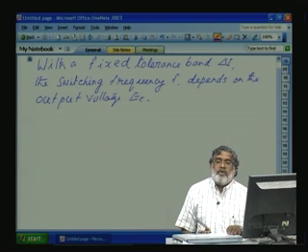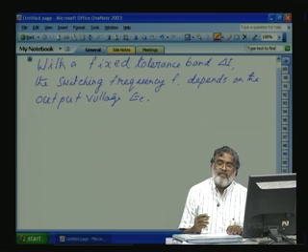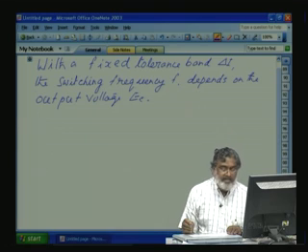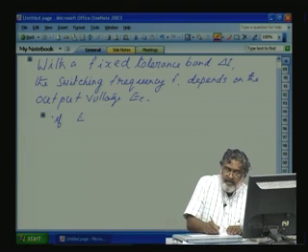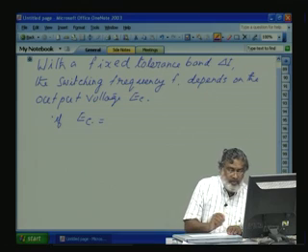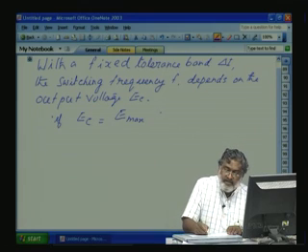Now, let us take EC is varying sinusoidally. That means for a 3-phase operation, where the single phase voltages vary sinusoidally, A, B, C vary with a 120 degree difference. So, let us take for a sinusoidally varying EC is equal to some E maximum into sin omega t.